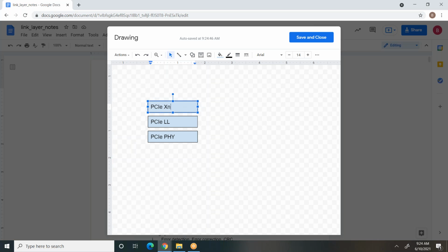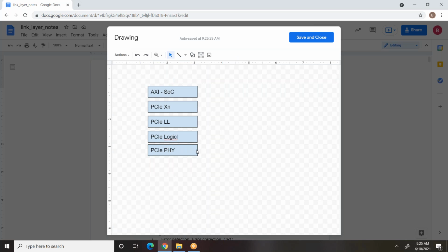Yeah, there's a physical layer in there, but this one, right? PCIe PHY. Yeah, between the PCIe PHY and the PCIe link layer, there's a PHY-MAC logical layer, PHY logical. Ah, okay. If you want to draw the layers, PHY logical, and then on top of this, you got an AXI bus or something and a chip transaction layer. The SOC talks to this PCI transaction, right?